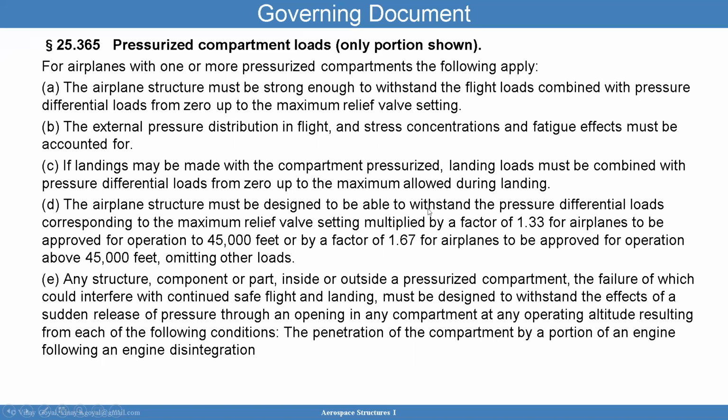The airplane must be designed to withstand the pressure differential loads corresponding to the maximum relief valve setting multiplied by a factor of 1.33 for airplanes to be approved up to 45,000 feet, or by a factor of 1.67 for airplanes to be approved above 45,000 feet.